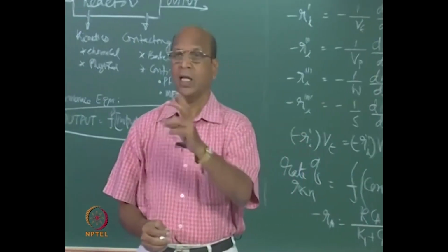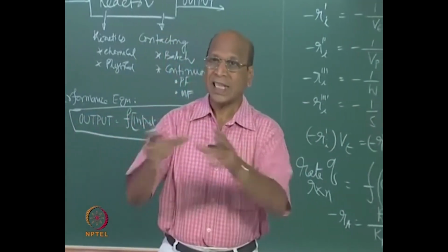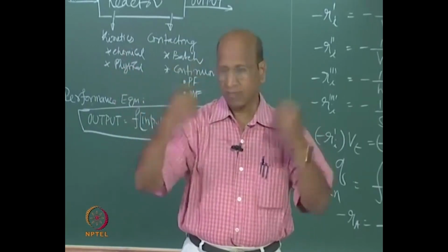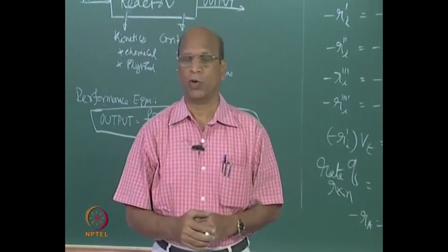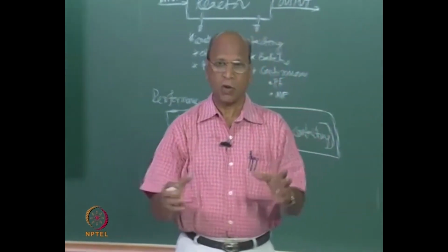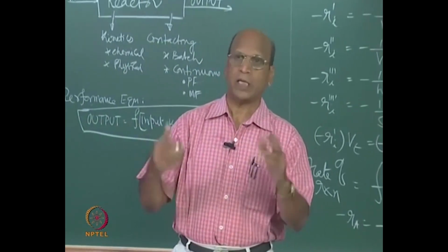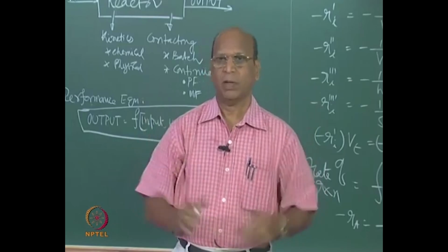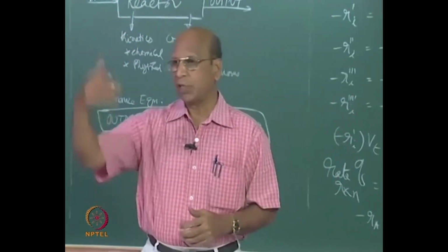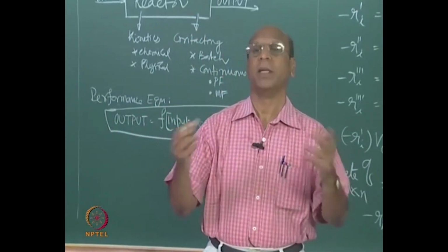It may be economical if you go for batch, or it may be economical if you go for continuous. This is the grey region where we cannot tell. But definitely, as he said, for 900 kg, 99% of the time we go for only batch system. So around 1 ton or less, we can easily go for batch systems, or 100 and above per day, again you can go for continuous. But in between somewhere you have to check the economics and decide which reactor is the best.